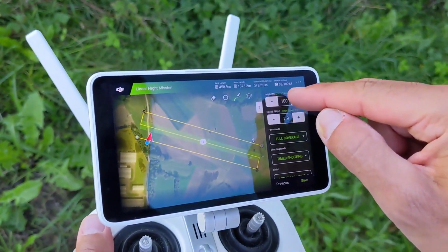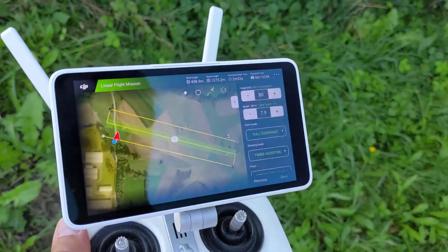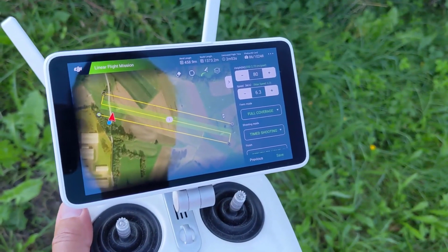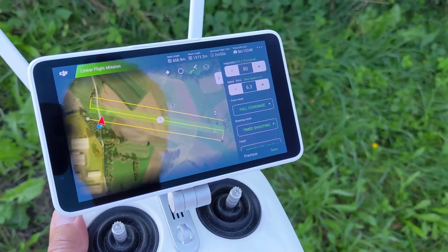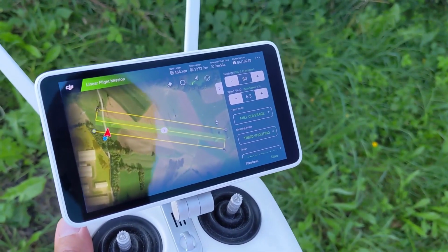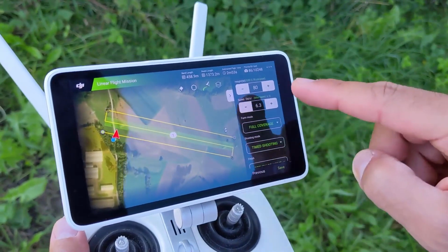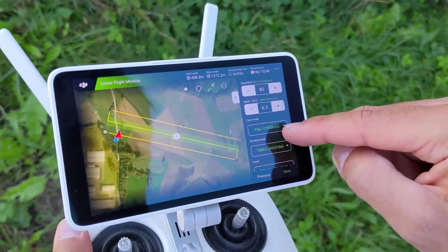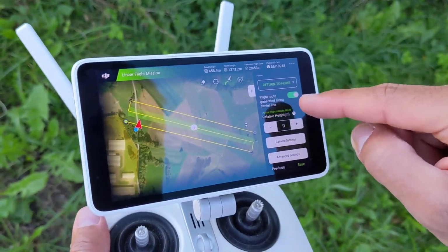Okay, I will set the flying height to 80 meters, because I need high resolution also on the power line cables. The power lines are probably 2 or 3 centimeters wide, and we need to see them accurately in the image. So the flying height is the first thing I changed, to 80. Everything else is okay here.